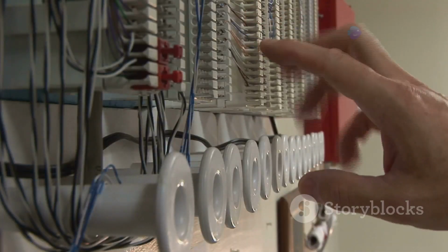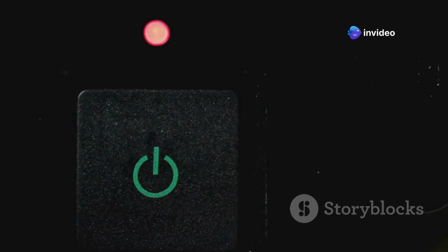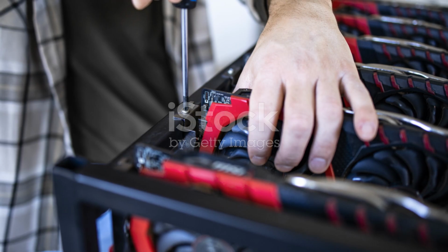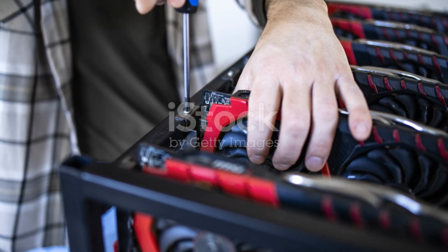For example, you can simulate an interrupt by connecting a button to one of the interrupt pins. Pressing the button would generate an interrupt signal, causing the 8085 to jump to a specific interrupt service routine. Understanding these advanced features is crucial for designing more complex microprocessor-based systems.